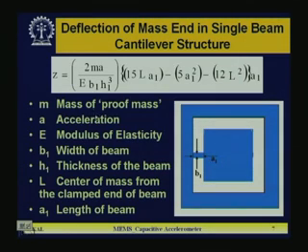So, if a is the acceleration, then with acceleration a along the Z direction, if we accelerate the whole structure, the seismic mass will move, some displacement will take place, and that displacement is Z, which is given by this relation: 2 m a over E b1 h1 cubed, into (15 L a1 minus 5 a1 squared minus 12 L squared) multiplied by a1.